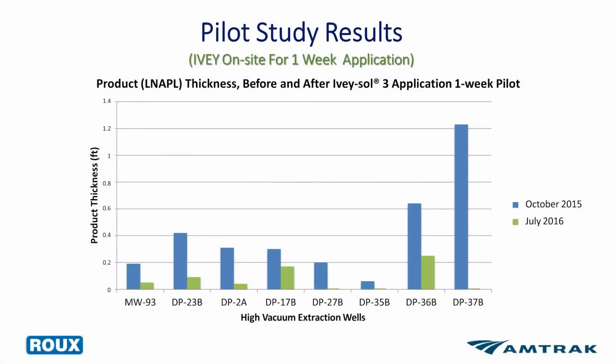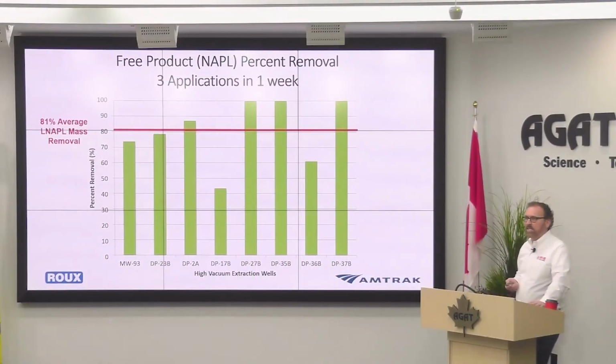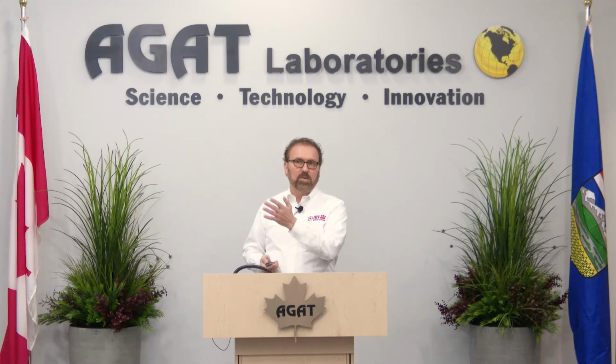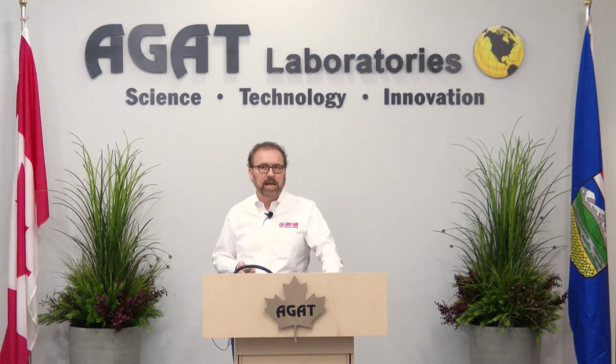Here's the before and after thickness of the free phase at the site. And what I'd like to show people as another example is the mass removal that we realized in that 1 week. An average of 81% mass removal was realized. Not bad. And then the nice part about that, as I showed in the previous slide, we did this in late October. By July of the following year, there was no change in what we had removed. There was no rebound, so it held consistent.